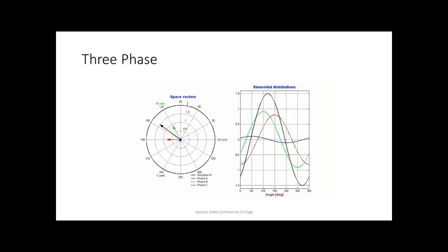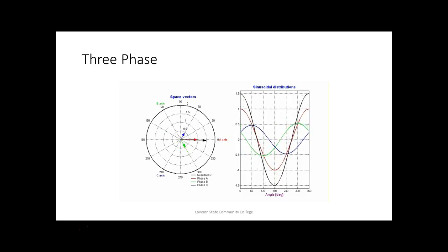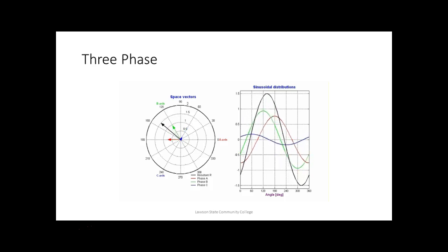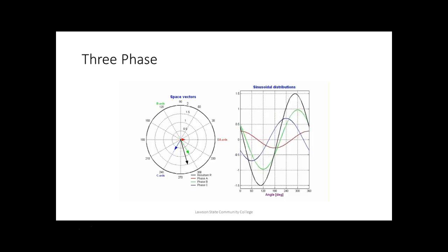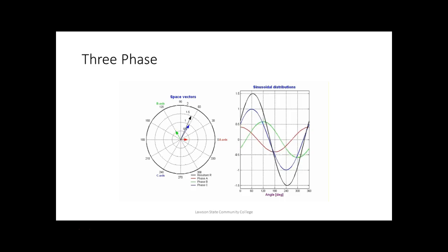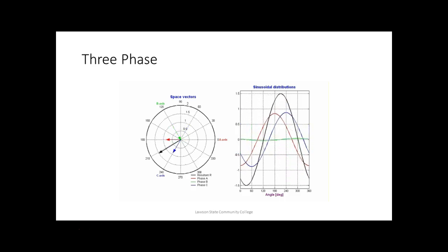This is showing the angles, how it builds up on these sides. It's pretty amazing. So the red field plots the polarity to this. But the maximum power always occurs where all 3 of them kind of cross. Now, how would I change this direction? Well, I got to make the power field move in the opposite direction. But this is 3-phase right here.